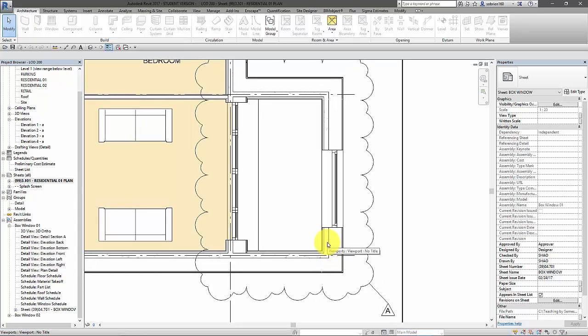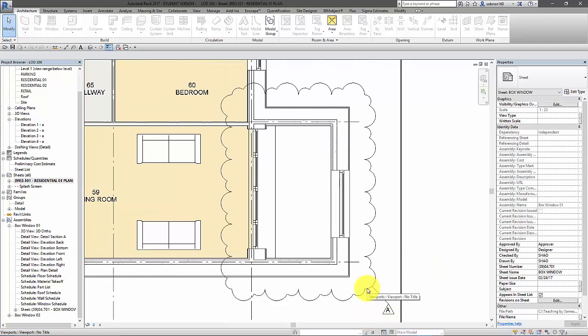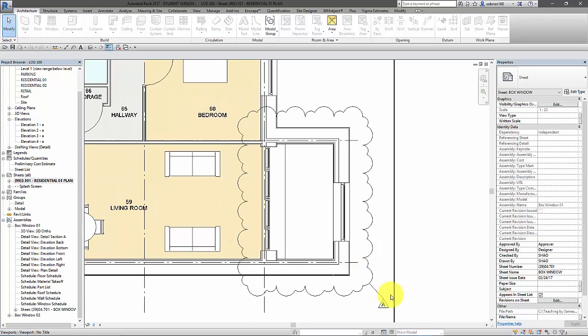The thing to remember about revisions is you never make revision numbers if they're just revisions among the design team yourself, because that would be crazy because you're revising all the time, basically. The only time you make an official revision number is if you send it out of the office, because then it becomes a legal document. So you need to have a strong record of what's been going on in the design.